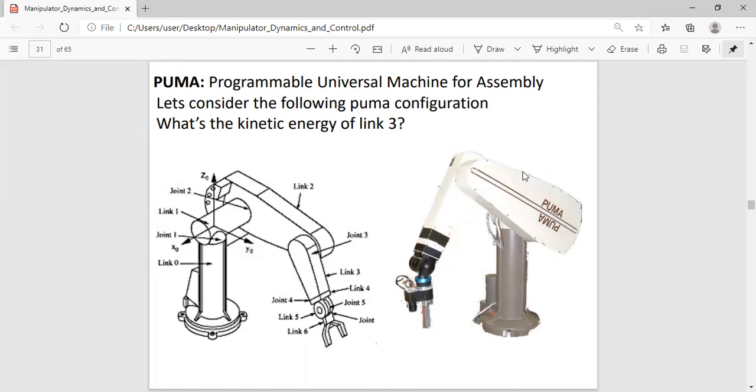I think everything is going to be simple here in terms of finding the potential energy of the system. It's very easy. We'll simply locate the center of gravity of the various links, and we know the potential energy will be equal to mgh. Next step is we need to find the kinetic energy of the system. Each rigid body will actually have two kinetic energies, right? It will have a translational kinetic energy, or 1/2 m multiplied by the velocity of the center of gravity squared, right? So these are easy. And then you have 1/2 I omega squared.